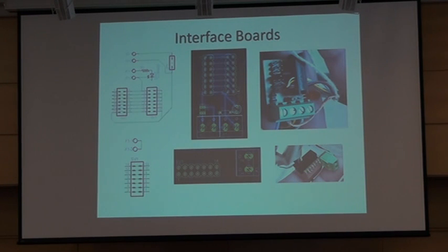So here's the boards we designed in EagleCAD. It works pretty simply. Basically, this pin is an input for the DAC, and it's always pulled up with an internal resistor to the 5 volts, unless, of course, you short it to ground, which happens if the cable is conducting all the way through.